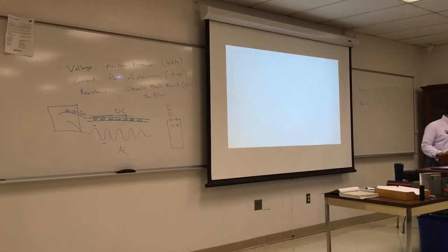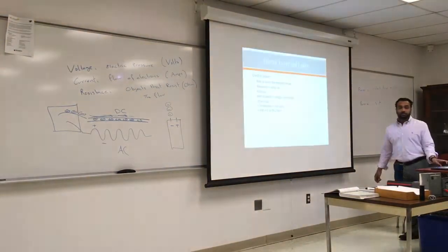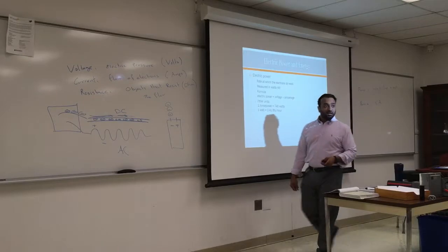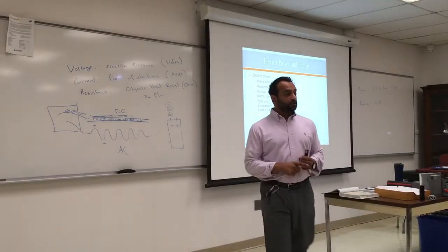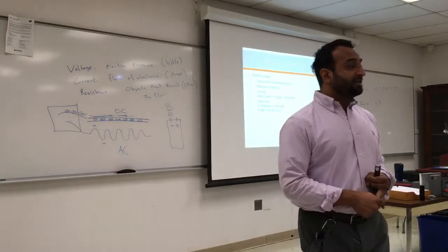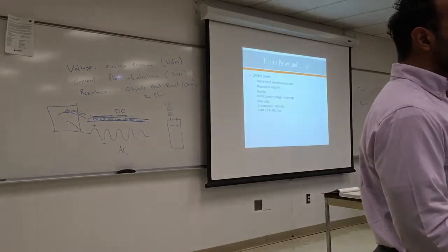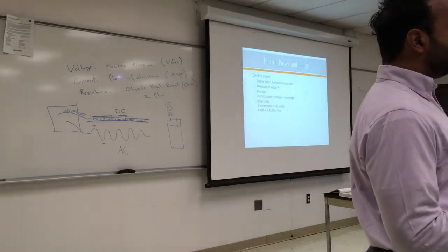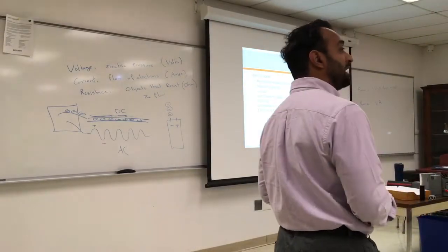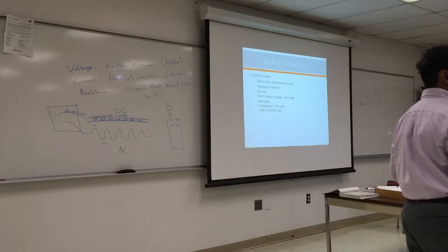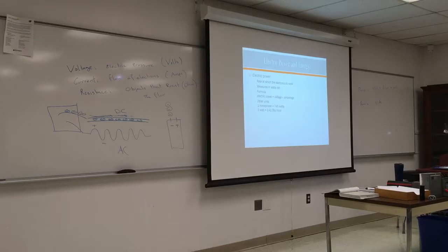It makes a lot of difference, and it makes up a good and bad technician. You have to read the voltage. What is your consumption? If you have an AC that is 220 and you plug it into 110, it's not going to work. You have to understand the hot legs and the neutral legs. You have to understand the phase. We'll talk about the phase later on, which is single phase, double phase, and 3-phase equipment.